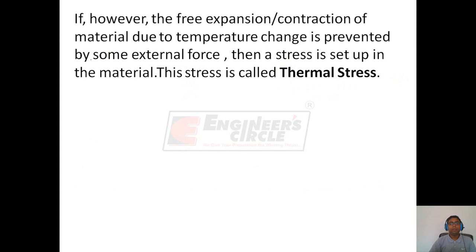Free expansion will take place when temperature increases and contraction will take place when temperature decreases. If the free expansion or contraction of the material due to temperature change is prevented by some external force, then a stress is set up in the material. This stress is called thermal stress.